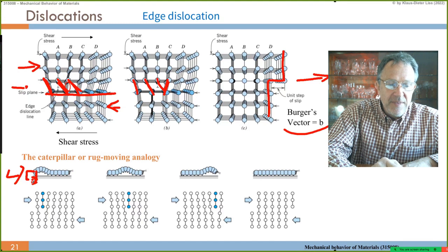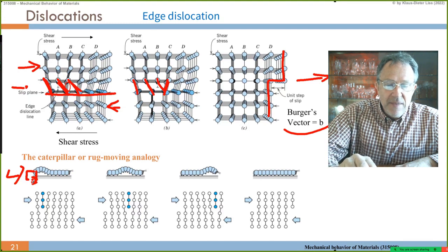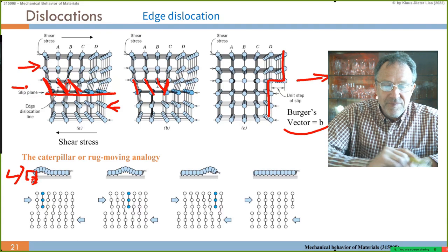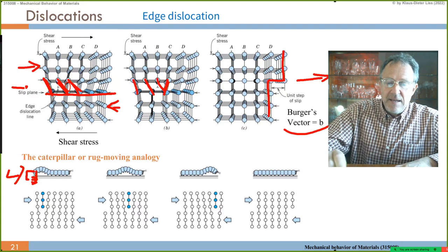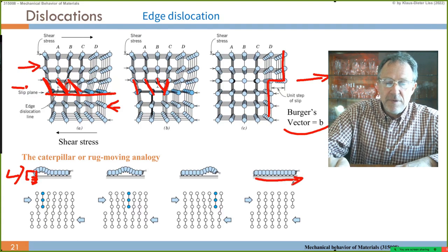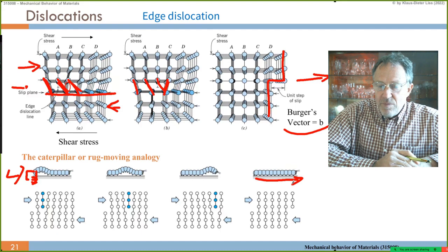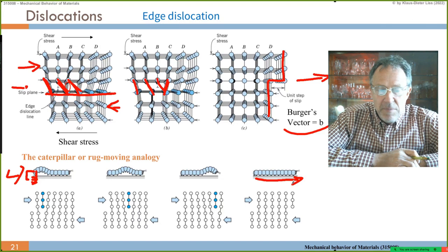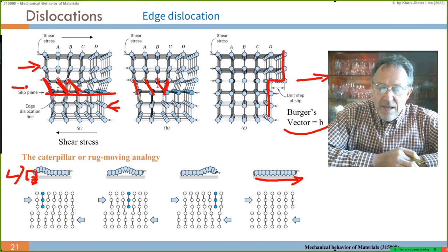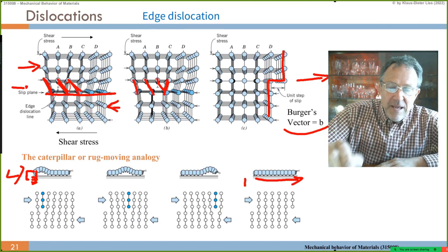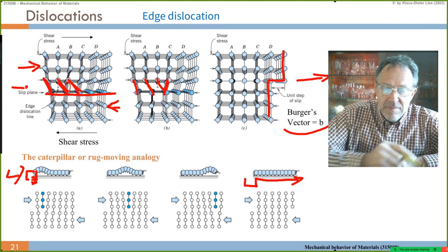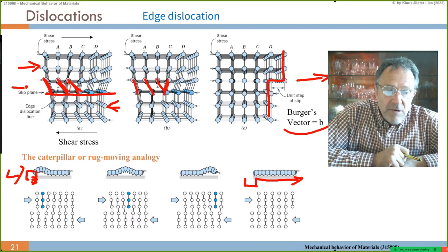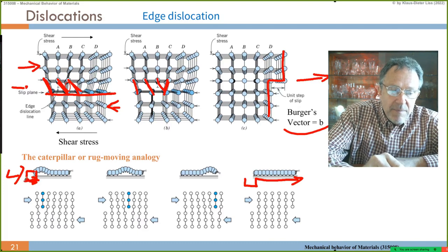And then this buckling goes through, and the buckling advances to the head, and eventually you come up with a strain-free caterpillar again, so a flat, long, one-dimensional caterpillar, which has been displaced by the Burgers vector, by the amount it lifted up the tail at the very beginning.